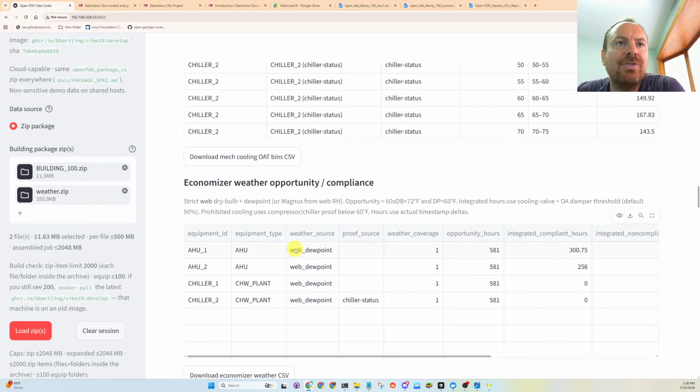I do have a calculation that I'm doing on outdoor dew point too. That's from my previous employment, just doing algorithms. We had a couple of really old buildings that were school districts, and one of the other engineers came up with a strategy to, instead of using return air enthalpy economizing decisions, because these sensors were existing way beyond 5 years, or what the original manufacturer had calibration for, return air humidity sensors and outdoor air humidity sensors local to the building are really notorious for being out of calibration.